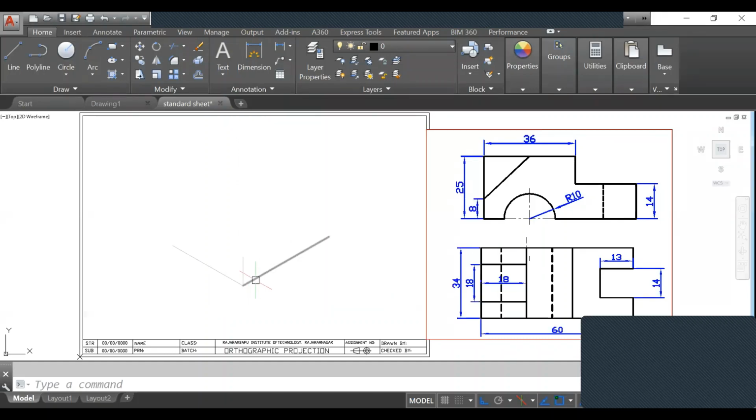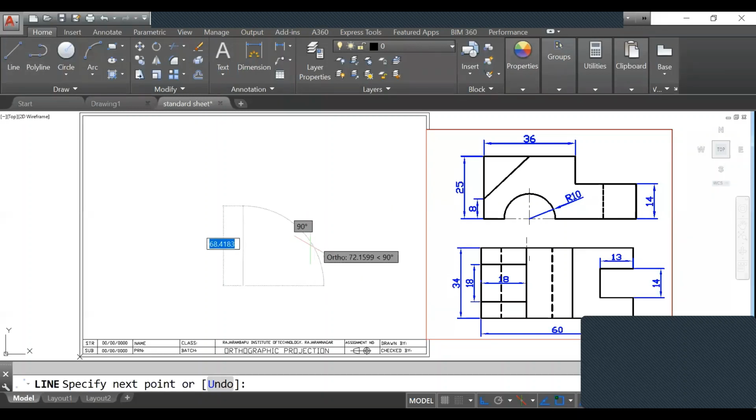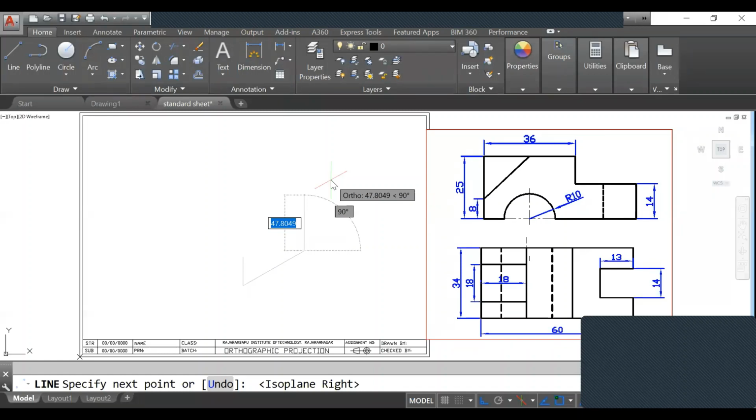Getting? So first of all, you have to draw the front view here. I will just delete and draw the length. Front view length means it is required to draw in the front view mode. So you can just change the mode. This direction 60. Then again here Control E. So height I will prepare 25 here.